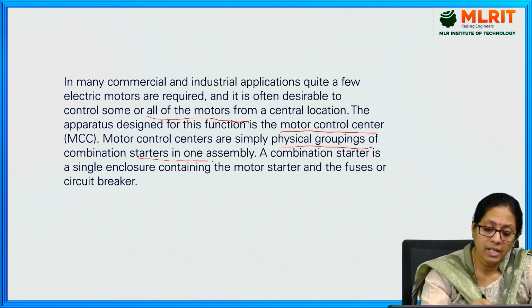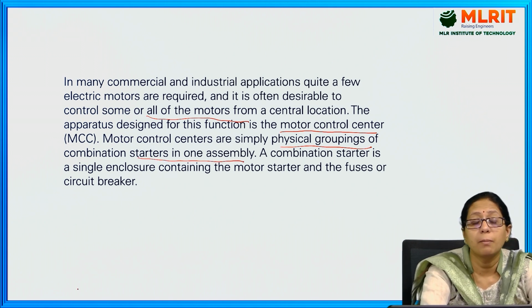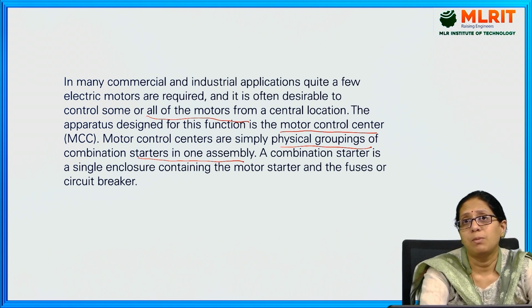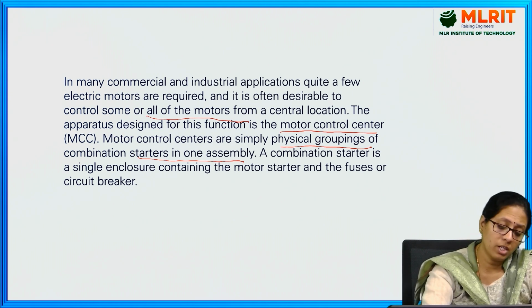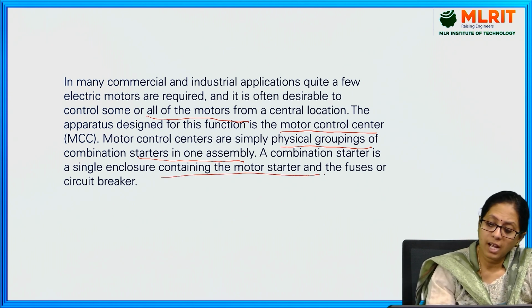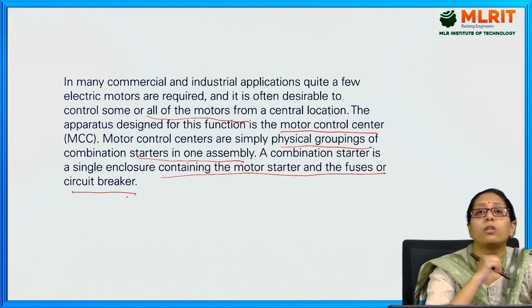in one assembly. That means different starters are required to start the motors. So all these combinations are connected to the MCC. The combination starter is a single enclosure containing the motor starter and fuses or circuit breaker.